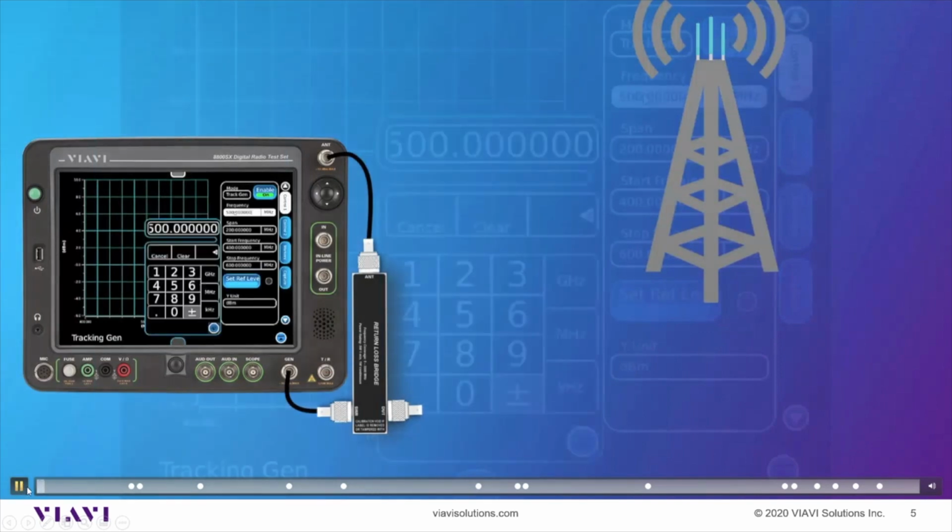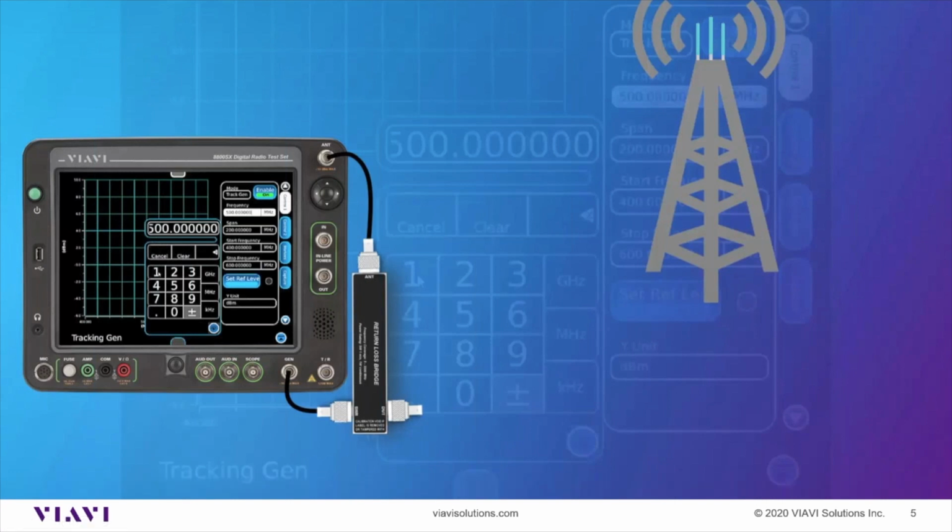So again, what we have here is our return loss bridge. We used it in the last measurement or alignment that we did on our duplexer, and now we are using that same device to check our antennas. Basically what I'm doing here is I've got the return loss bridge set up, and when you do this, you have an open on the device under test port. So it's a very simple calibration. On some devices, you have to do a short, open and load, and it takes a little bit of time to do that. So this is very simple. You just hook it up.